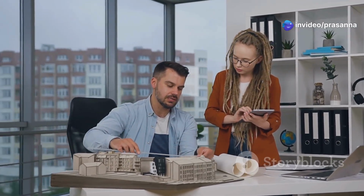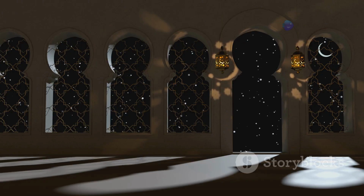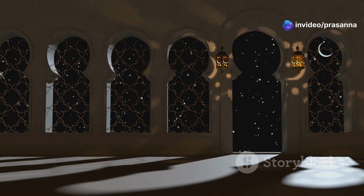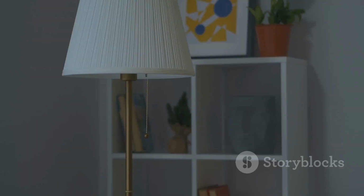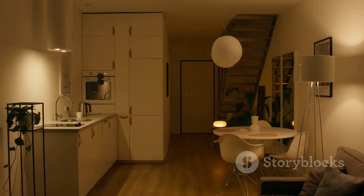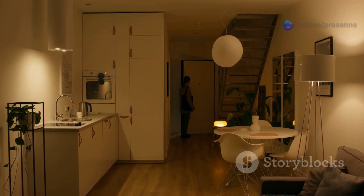Beyond furniture, consider lighting. While SketchUp itself has basic shadow casting, you can use rendering plugins to create highly realistic lighting effects. These plugins simulate how natural and artificial light will interact with your space. You can add light fixtures from the 3D warehouse. Think about the mood you want to create in each room. Warm lighting for living areas and brighter functional lighting for kitchens and bathrooms.